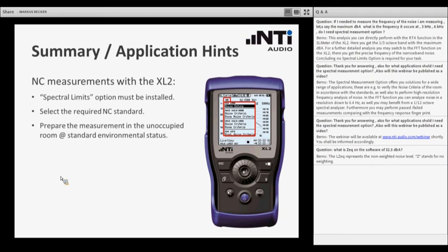So you should not execute such a measurement, for instance, at midnight time when we are looking for the background noise in a normal office where people are working at daytime, but we should execute the measurement actually during daytime when the outside traffic, for instance, is as it is normal. It's just no people in the room, but the external situation should be as usual.